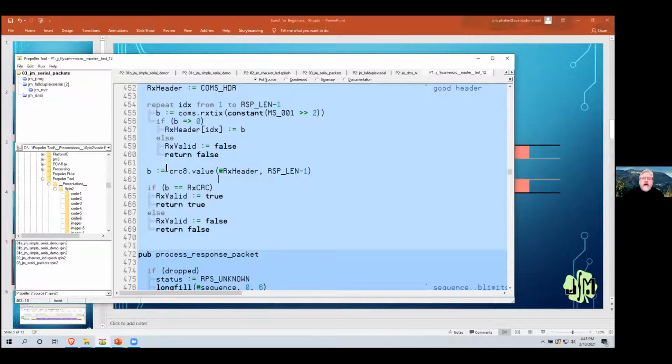So you'll see now, this was the fix. Once I figured out that was the problem, then what I did was I just made an assembly version of that. So it went from, I think, 7.5 milliseconds to calculate a CRC down to 30 microseconds, and suddenly I didn't have any more broken timing problems, and we got everything working nicely, and it's off to the customer now.